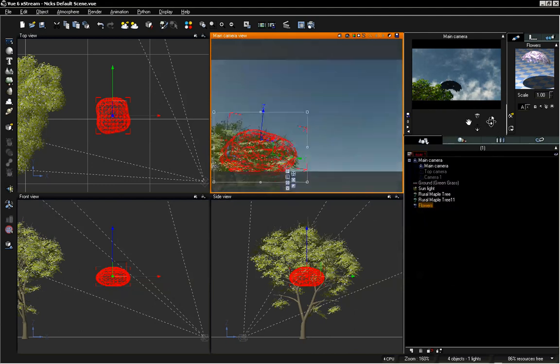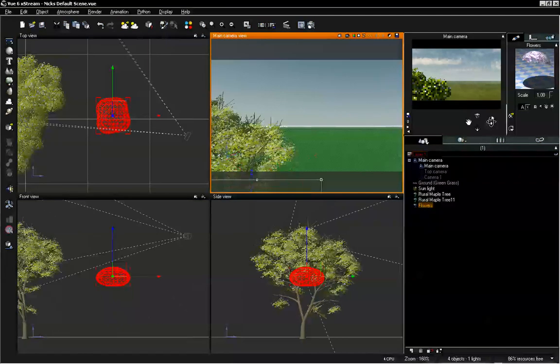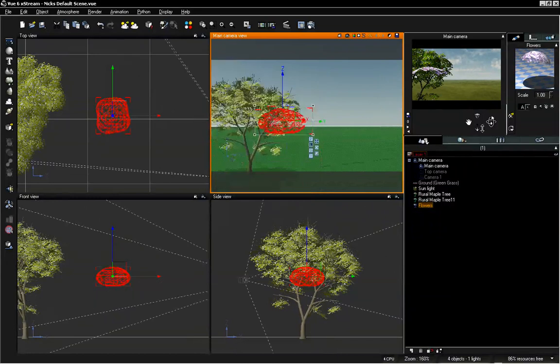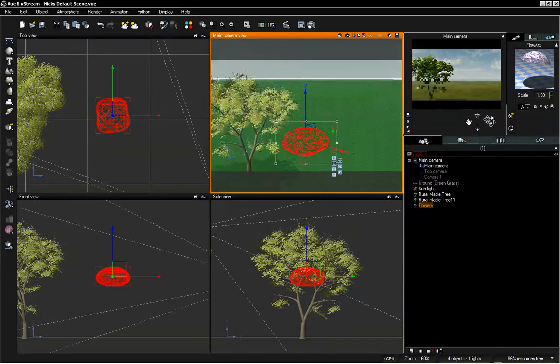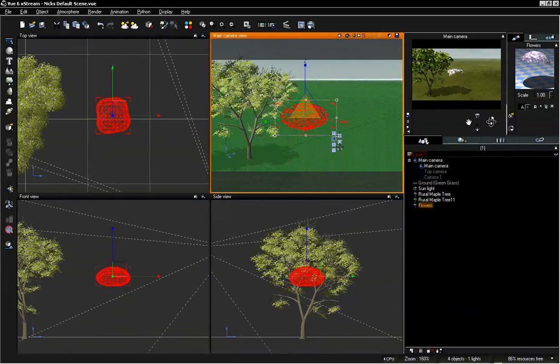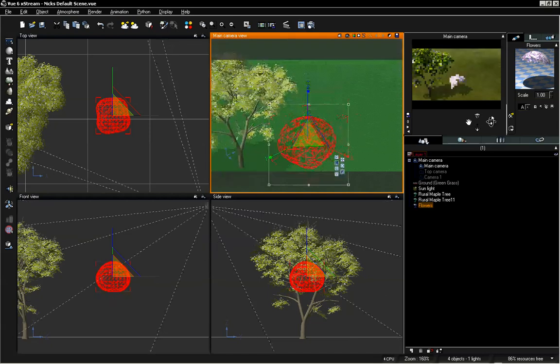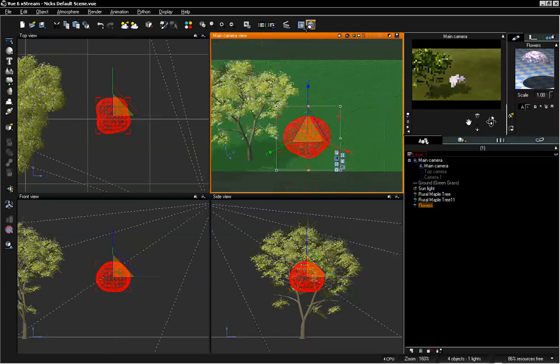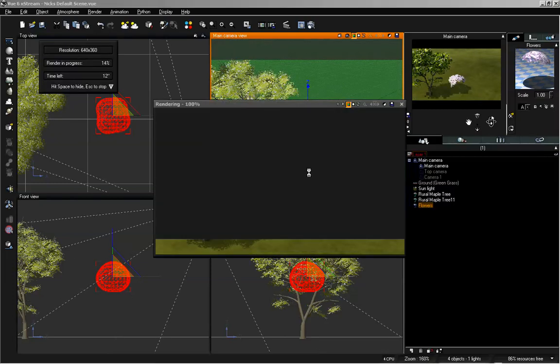And after looking underneath now, it looks like that did remove the bottom part of our object and our surface. So it looks like that is going to work out just fine. I'm going to switch to our scale gizmo and just stretch this up on the Z to give us a little more depth up and down. And now we can go ahead and render that and take a look.